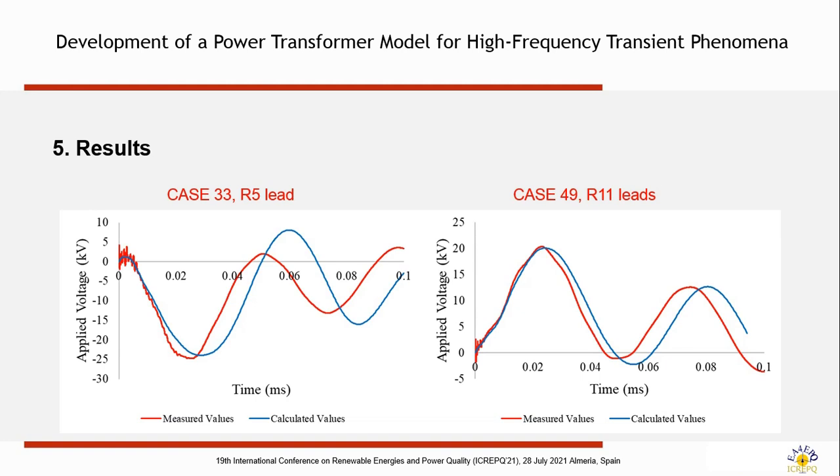Another typical uncertainty could be because these tests were taken with a transformer not immersed in oil, just in air, but some materials, such as the pressboard or paper of the insulating structures, could be impregnated in oil, which is not the same as in air. So the permittivity value changes a bit. But anyway, in general terms, the correlation was quite good.